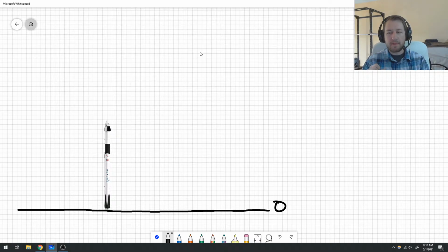The data that the predict step is giving you just comes from saying, oh, well, I know my state last time step was this kind of state, right? Like I know what my position was last time step, and I know what my velocity was, and I know that if I waited this much time, your time step time, then based on the velocity, my position should now be this, and my velocity should now be this. So we're predicting where the rocket should be based on previous data. But then the measurement comes in at a time step as well and tries to correct and say, hey, well, actually the data is this.